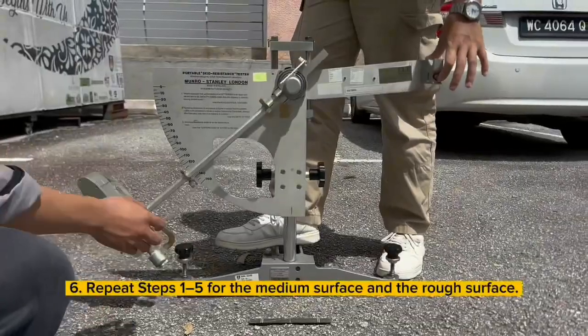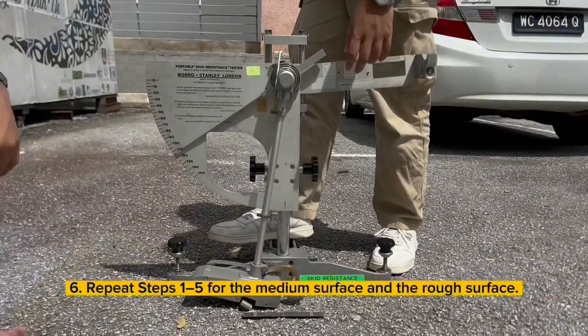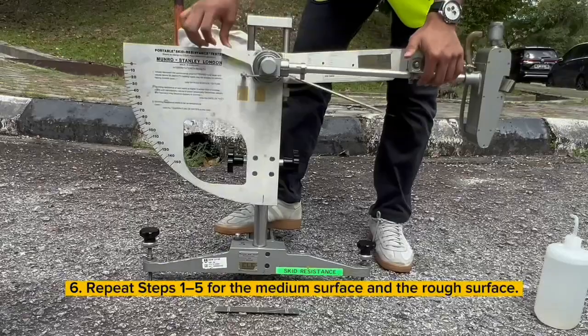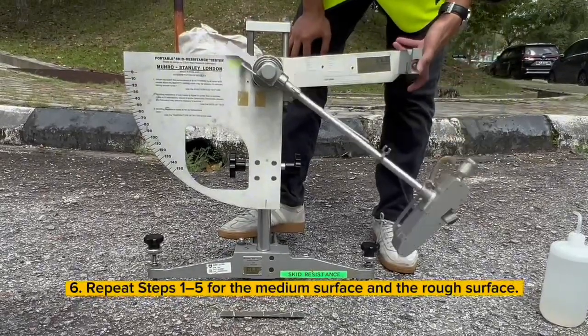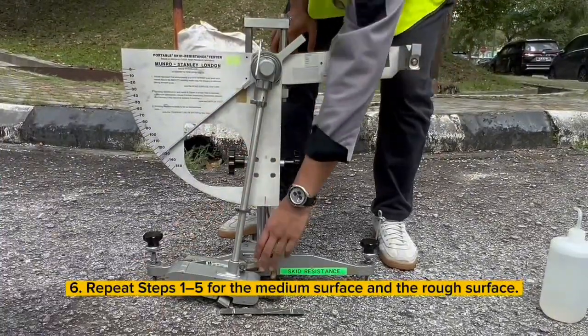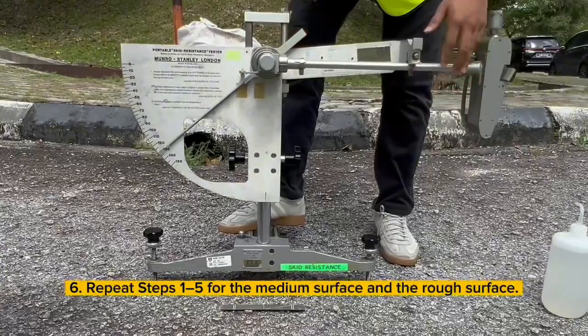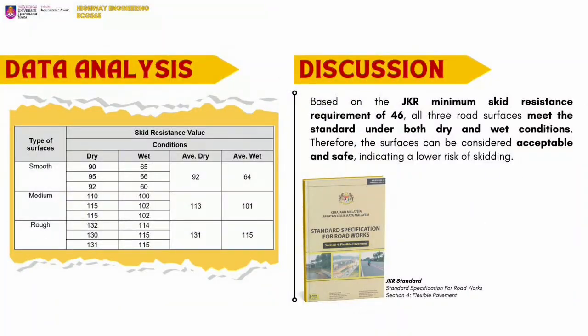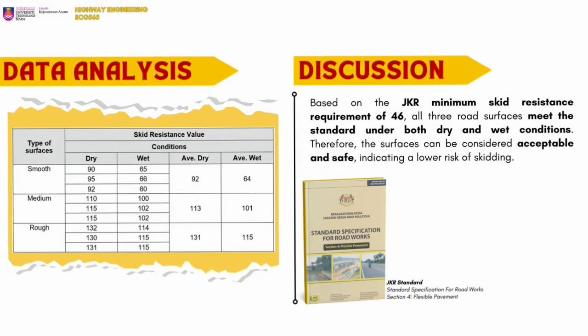Repeat steps 1 to 5 for the medium surface and the rough surface. This is the data analysis that is tabulated in the table. Based on the JKR minimum skid resistance requirement of 46, all 3 road surfaces meet the standard under both dry and wet conditions. Therefore, the surface can be considered acceptable and safe.